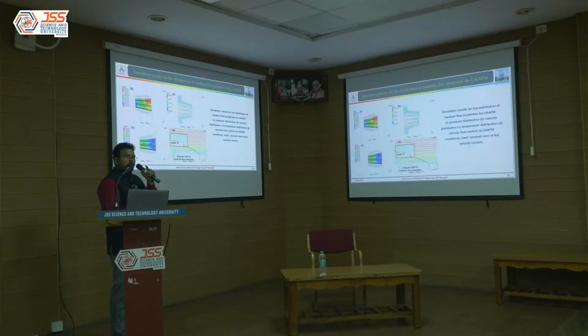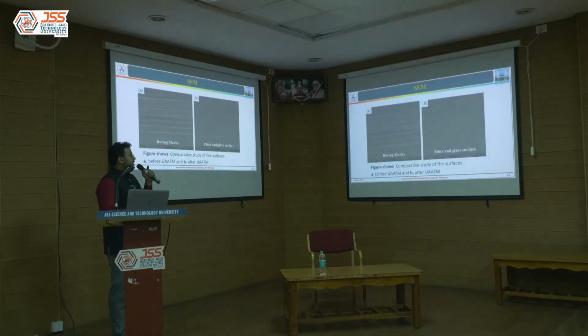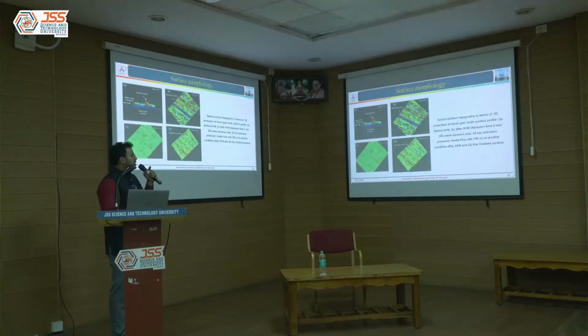It also shows the penetration of abrasive particles hitting at an angle theta. And we observed under a scanning electron microscope how the boring marks and the grinding marks were finished by using ultrasonic assisted abrasive flow machining.